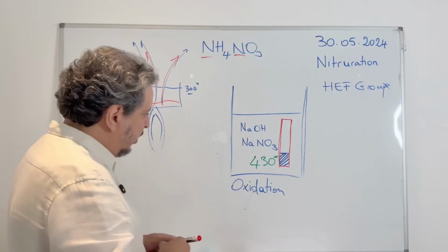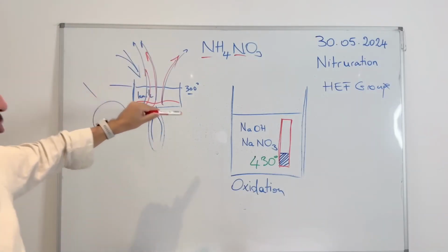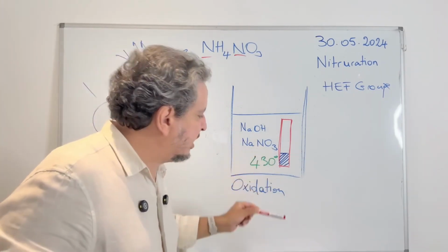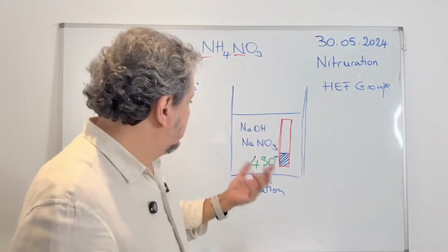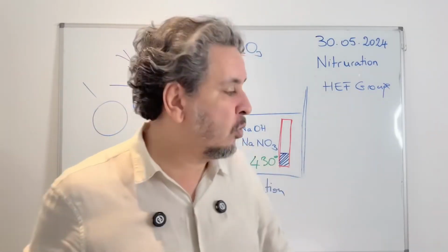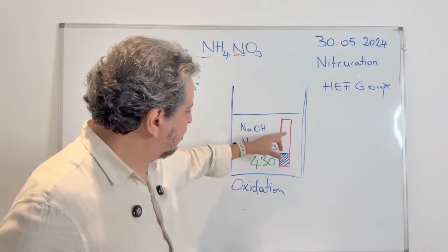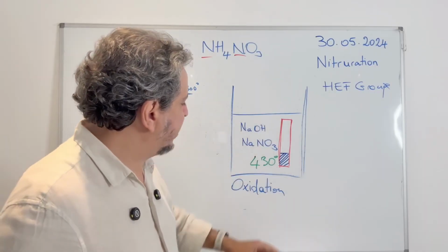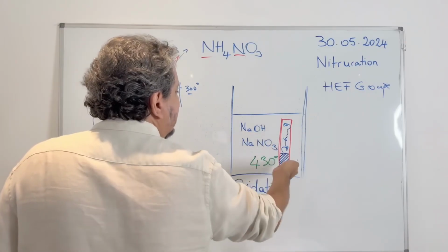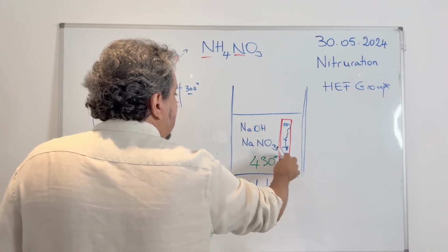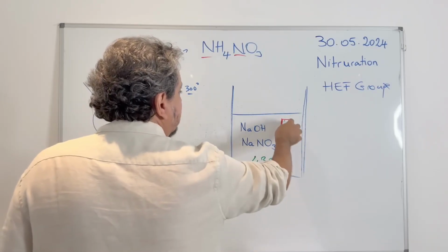So there was water in there. Remember that. We're pretty much following the same logic here. So we have water trapped inside the tube. When they put the tube in, there was, I don't know, 2 or 3 liters of water inside. The temperature was 430 degrees. What did the water start to do? The water started to heat up. It immediately vaporized inside the tube. But since it couldn't go anywhere, what happened? It started to increase the pressure in the tube and leak a little bit from the top.